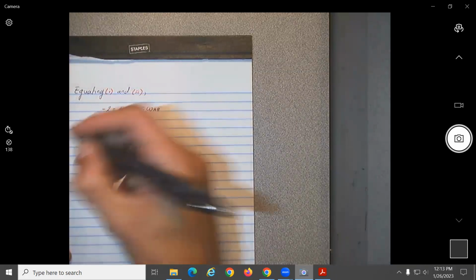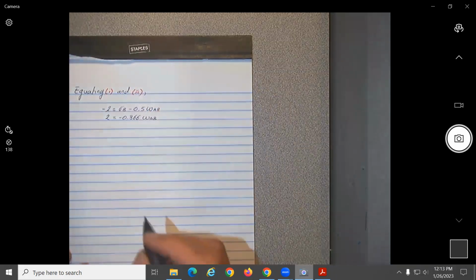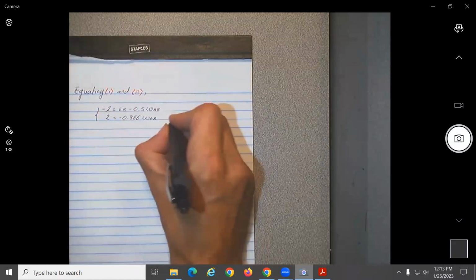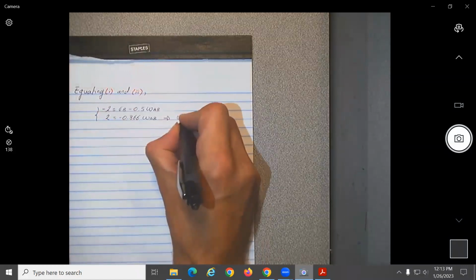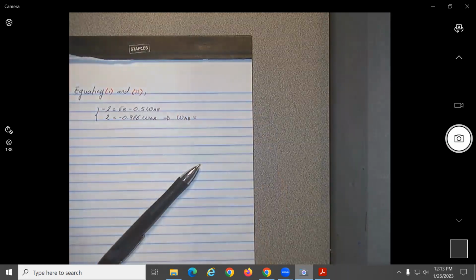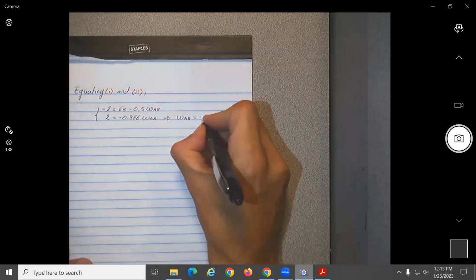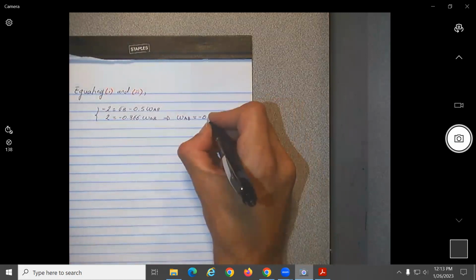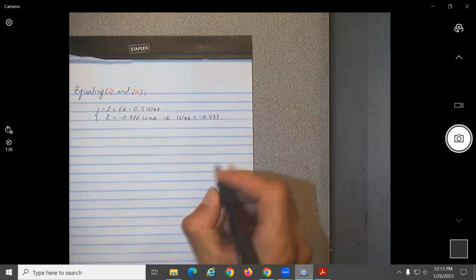Should be 0.667, but it doesn't matter, just for the example. So that's it. So what can we do over here? We can solve right away this one for omega AB. Maybe we should have kept the square root of 3/2 because this should be equal to what? Minus square root of 3/4, no? But how much would that be? Negative 0.433. Yeah, negative 0.433. All right, radians per second.